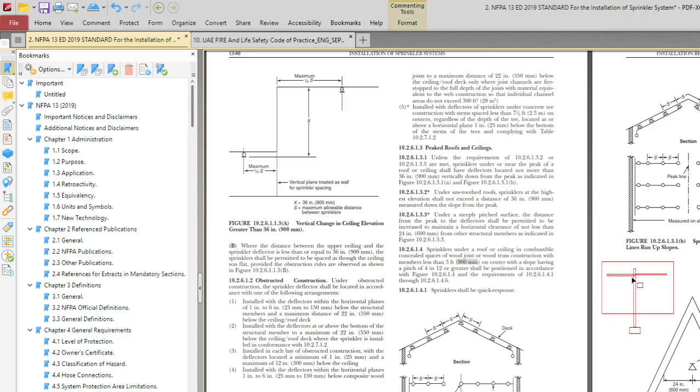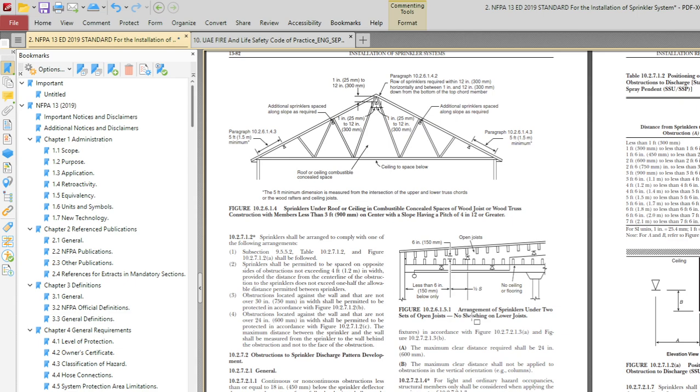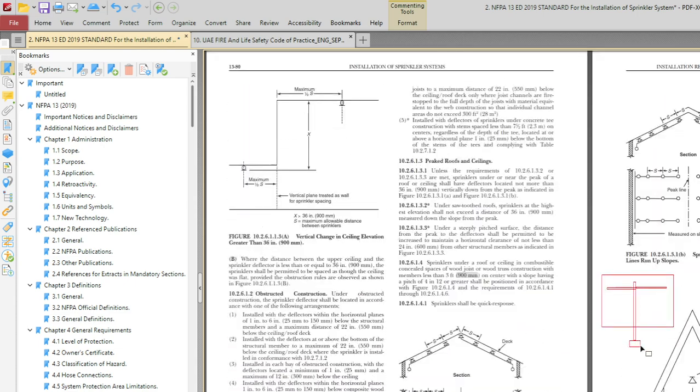Okay, so remember, as per the sprinkler calculation, we are going to have a maximum of 8 sprinklers in one branch for extra hazard. In one branch, the number of sprinklers should be 8. That one we have seen somewhere back. I think you remember, right? Yeah, I remember it. Okay, now you take one, total 8 sprinklers, and here you have 8,